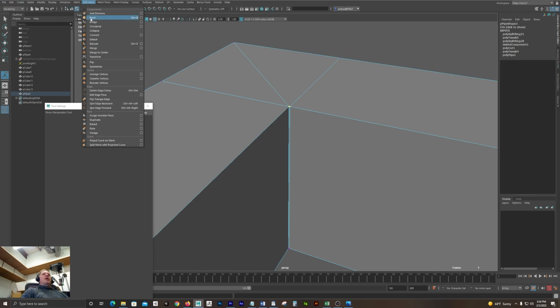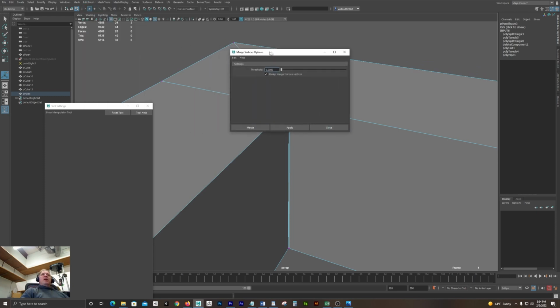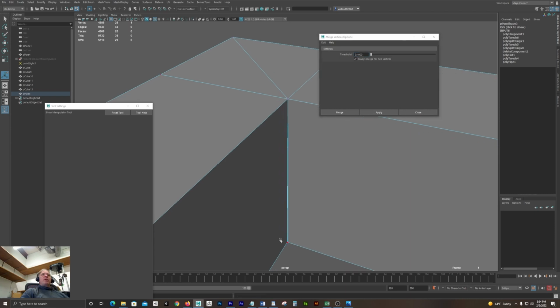and I'm going to go to Edit Mesh Merge, this case Options box, and wow, my threshold is at 0. That's weird. You should default to 0.1. I'm going to say Edit Reset. Yeah, default is 0.001. That's normal. I'm probably not quite within that threshold, so I'm going to say 0.1 centimeter. And I hit Apply, and you can see in my heads-up display, those three became 1. Marquee select down here. There's my heads-up display saying 3. Hit Apply. There we go.